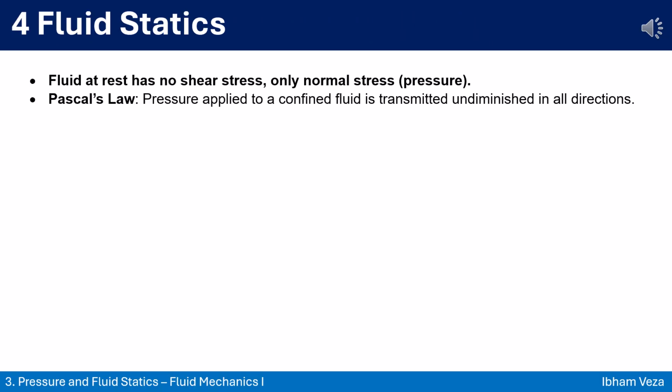4. Make fluid statics easy to remember. Here's how to keep fluid statics simple. When fluids are at rest, they don't move sideways, meaning no shear stress. They only push straight out, which we call normal stress or just pressure. That's why you can float calmly in water. The key rule here is Pascal's Law. It says that any pressure you apply to a trapped fluid spreads equally in all directions. Like pressing a balloon. Push in one spot, the whole surface pushes back equally.